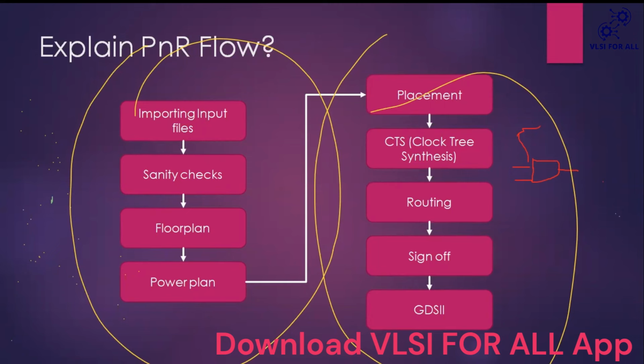We have to spend more time on CTS to learn. It is interesting and a bit difficult also. After doing CTS, we have to fix hold violations majorly. And anyway, we fix setup violations at every stage.